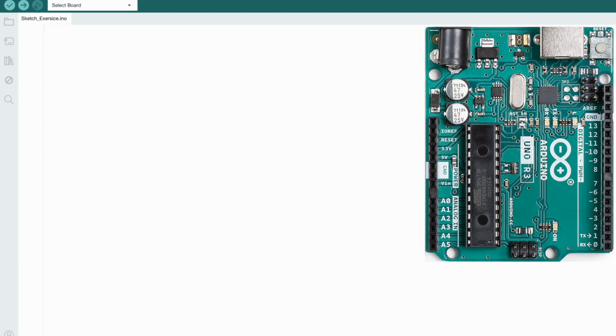Right off the bat, let's complete our Arduino code that we're going to need. This is what we're going to ultimately load into the Arduino board. The first thing that we're going to do is set up our analog pin that we're going to read in from, in this case A0. This is what reads in from our potentiometer. And then the baud rate, 9600. Again, we've seen that several times before when we set up our serial.